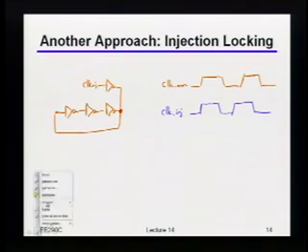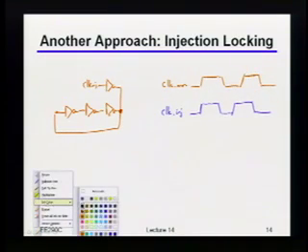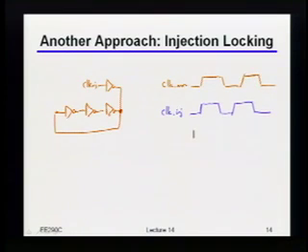So once this injection locking thing is, let's say, locked, meaning you've hit a steady state, then indeed what you'd see is that the phase of that thing would actually move earlier than you nominally would have expected it to be. Okay? Now, it won't be lined up with this, so maybe I'll draw that a little bit more carefully. But it'll actually be skewed. Okay?